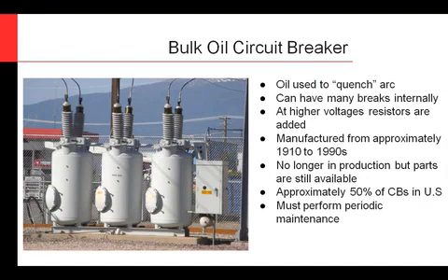So the next thing we have is something called a bulk oil circuit breaker. Once again, this is a dead tank design, and now oil is the actual insulation medium, and it's used to quench the arc. It flows over the arc during operation, during interruption, and it extinguishes it. The same thing as I mentioned before, it can have many breaks internally, but from a field testing perspective, it looks like 1 break per phase.